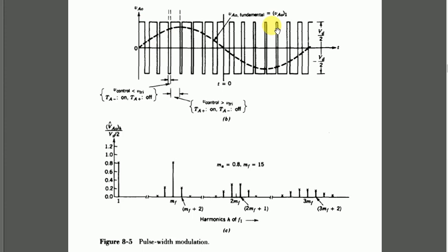Over here this has been labeled as the fundamental component of this switching square wave, and we can also see it present at this point in the harmonic spectrum. But as we had mentioned, not only will it have its fundamental component, but there will also be some harmonics and their sidebands, as we can see present over here.